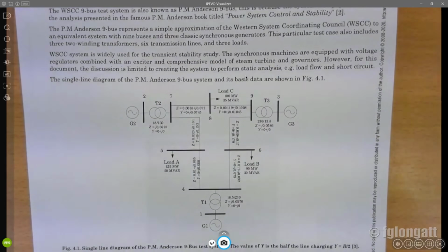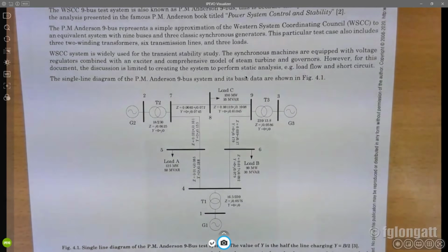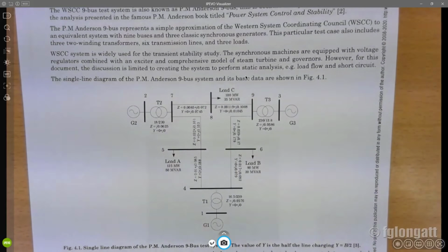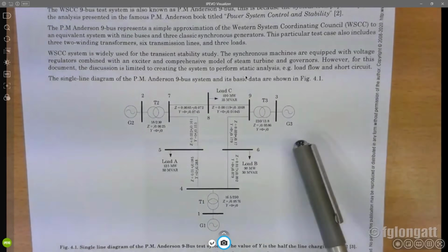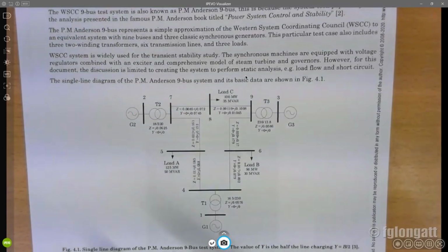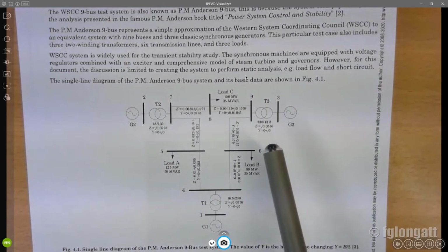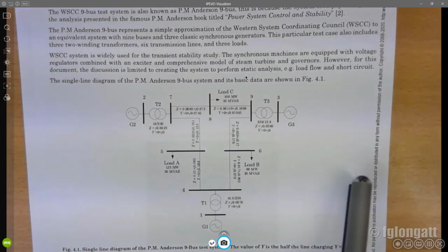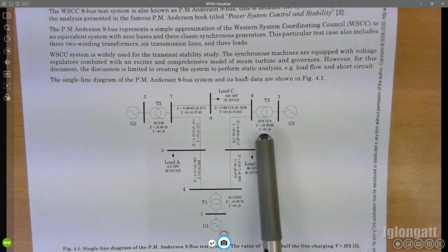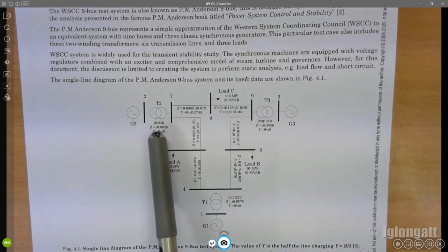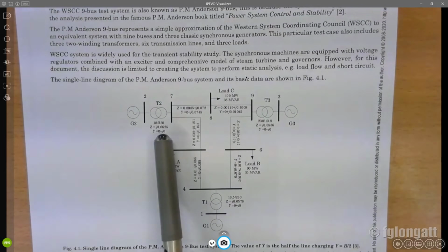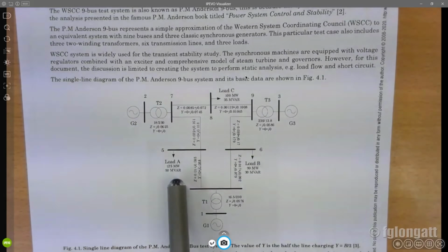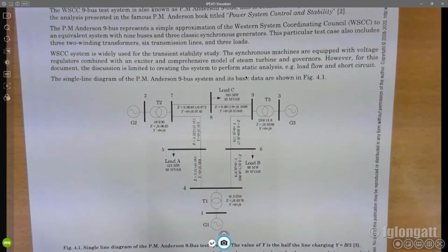I think you can see over there the famous single line diagram. In this single line diagram, you must recognize, okay, we have the graphical representation of all power components, but here also we have information about transformer ratio, what values are used for the transformer's impedance, load flow at the loads.